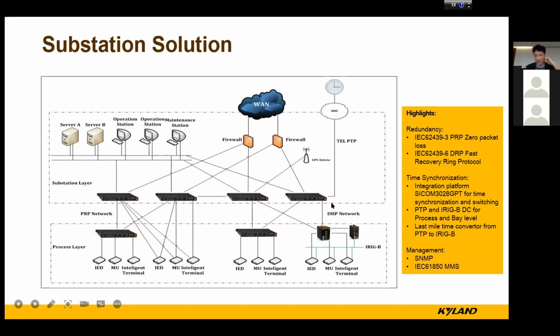And another highlight is that you can see that most devices are already PTP supported, but here some IEDs and module units are not PTP supported. So we can use a time converter to convert the PTP signal to the IRIG-B signal and finish the last mile synchronization.